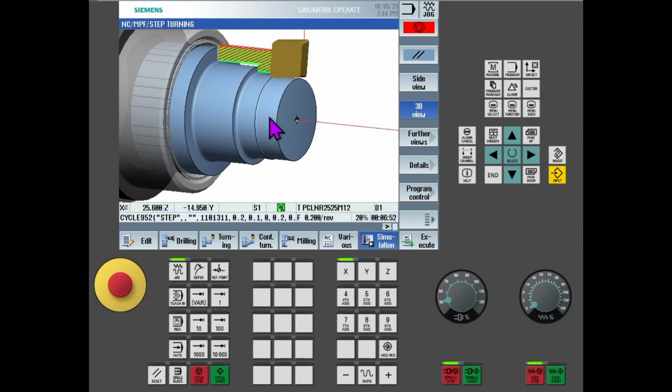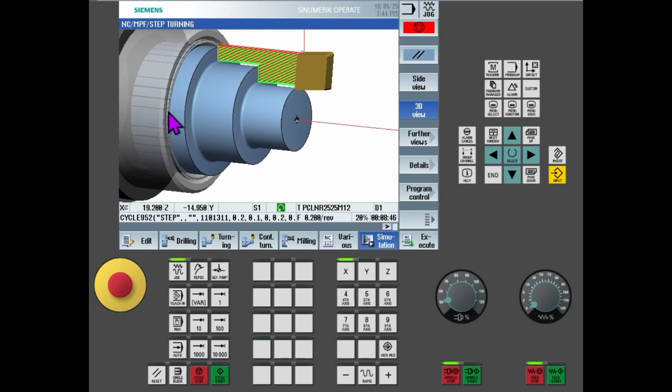So it is the amount of material we are keeping for the machining outside of the job. That is also necessary to check whether your tool is touching the chuck, or the tool is crashing with the jaws, things like that. So during the workpiece creation, this is really important. So here the diameter is getting changed. You can see it is taking the incremental depth of cut what we have given in the program. So that same incremental depth of cut it is following.